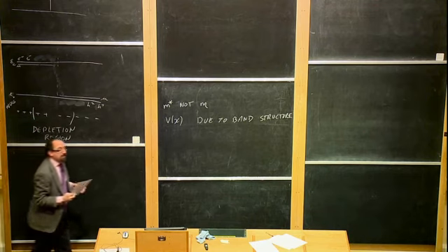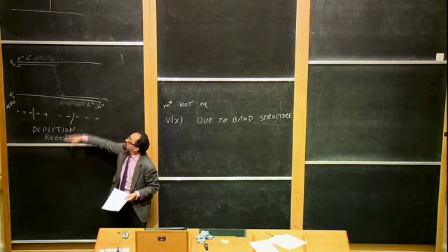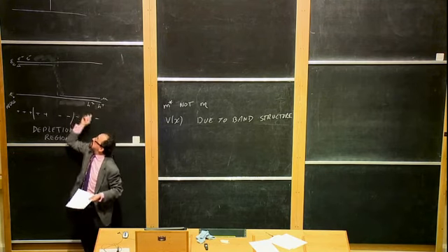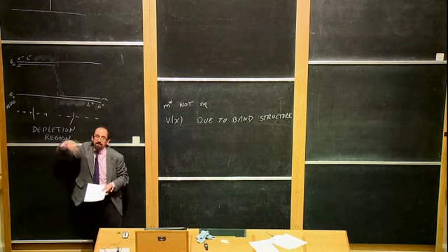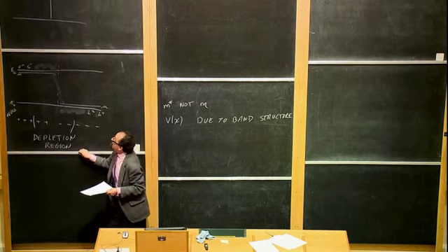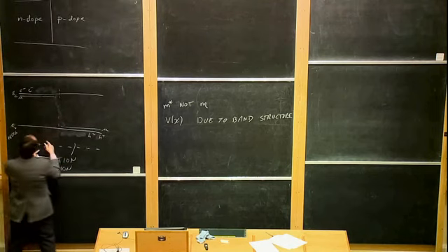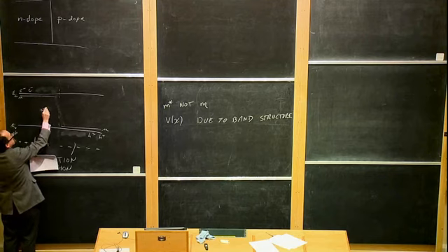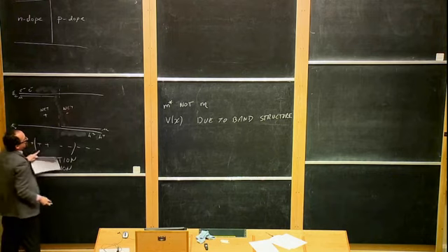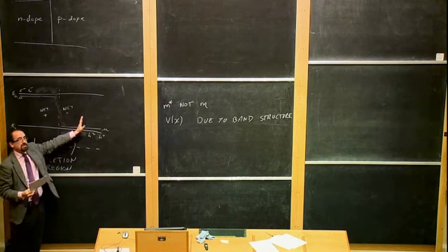Nothing moving around. So you might think that this annihilation would keep going, because the electrons are up at high energy and the holes are down at low energy, so we can just keep annihilating electrons with holes, keep emitting photons, and lower and lower the energy. But that's not true. In fact, it doesn't keep going, and the reason is that we're leaving a net charge behind. This region now is charged. This is net positive charge because of the dopants, and this is net negative charge. So as we start annihilating, we leave a charged region here and a charged region here.